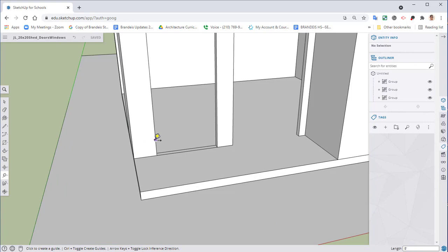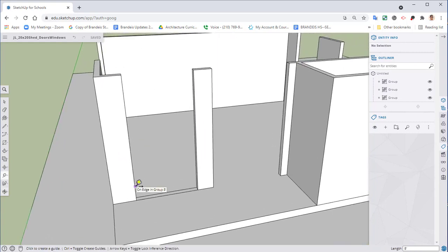So for the regular doors and windows, we want those to be 6'8". So we're going to go down here somewhere in the middle, or some arbitrary distance, as long as it's not the corner. The middle works most of the time, sometimes it doesn't. But I try to go somewhere where you'll see a little purple square. Go from there, pull up.